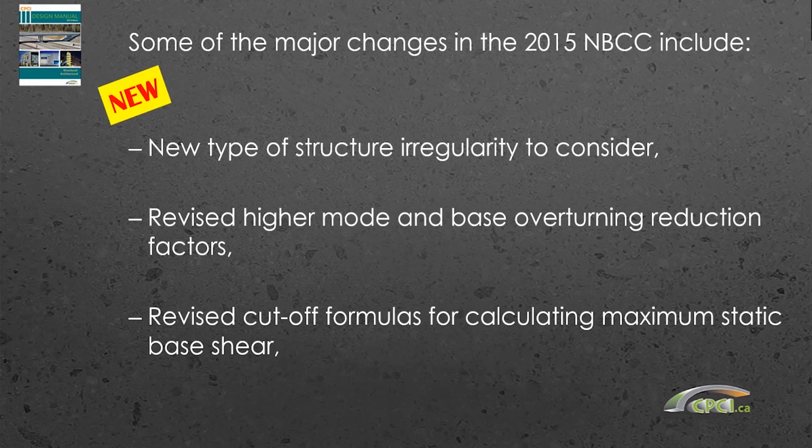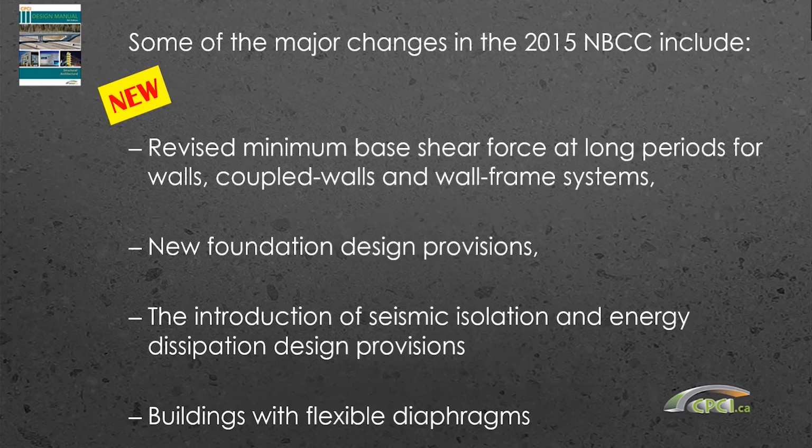So if you have any internal office spreadsheets and design tools that are currently designing to the seismic loads, those will be undergoing significant changes to incorporate the new seismic provisions and equations. There's also revised minimum base shear for walls, coupled walls, and wall frame systems, new foundation design provisions, and new provisions for seismic isolation and energy dissipation.